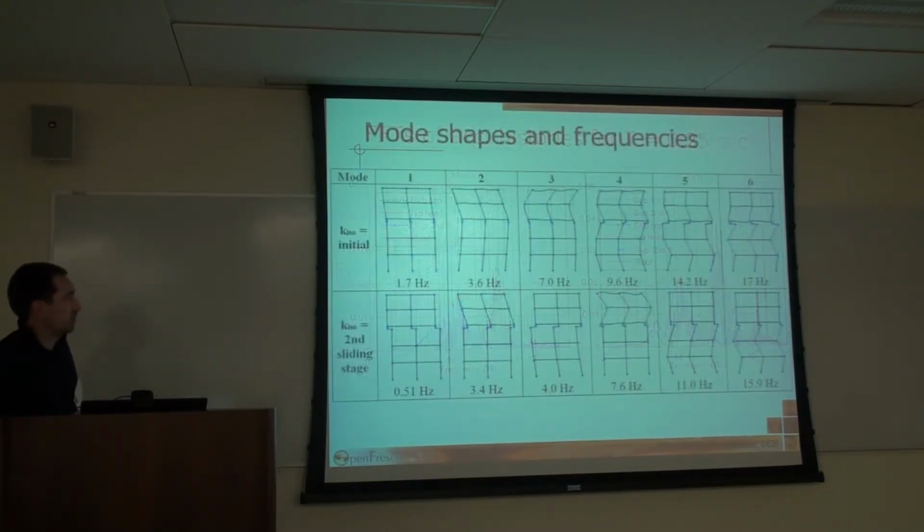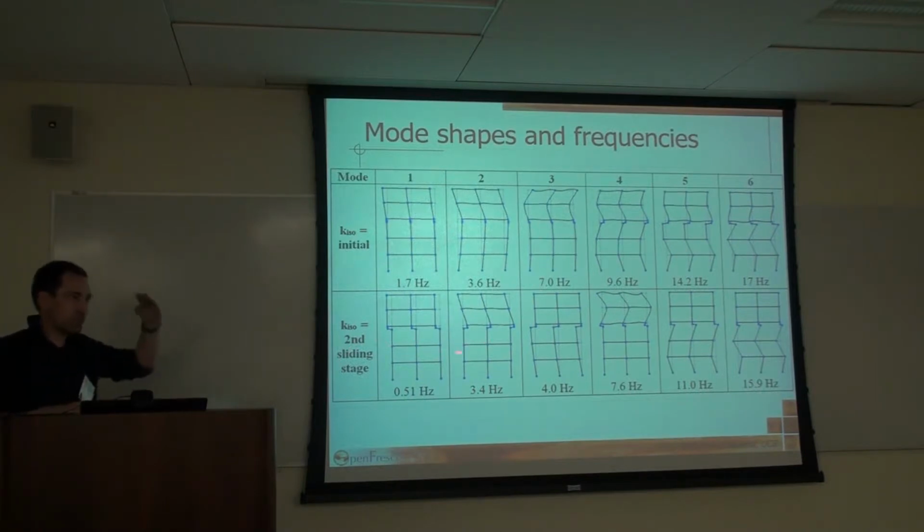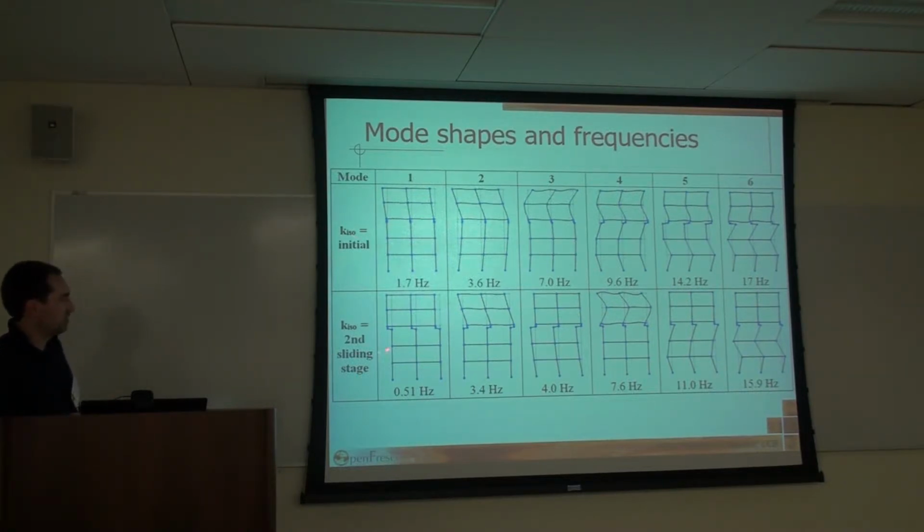And these really started having problems. So if you actually look then at mode shapes, and we did this to really investigate what was going on, because we have a triple friction pendulum isolator under the structure, this can respond either in its initial stiffness, the isolator, or the isolator can respond in post-yield stiffness, right, once the isolator starts moving. And so you can plot mode shapes assuming the initial stiffness or the post-yield stiffness.